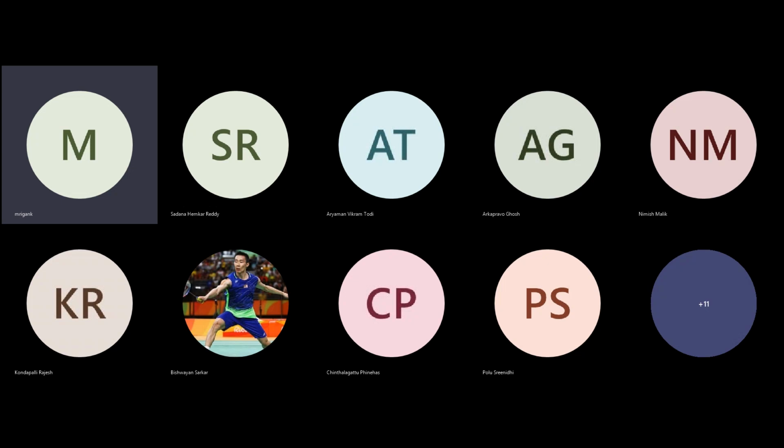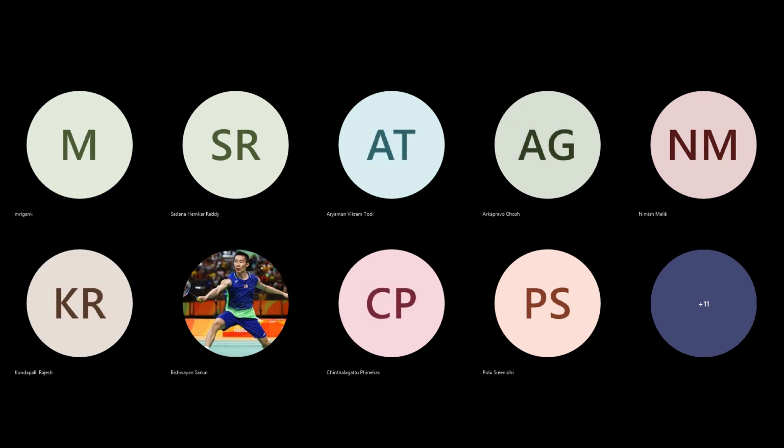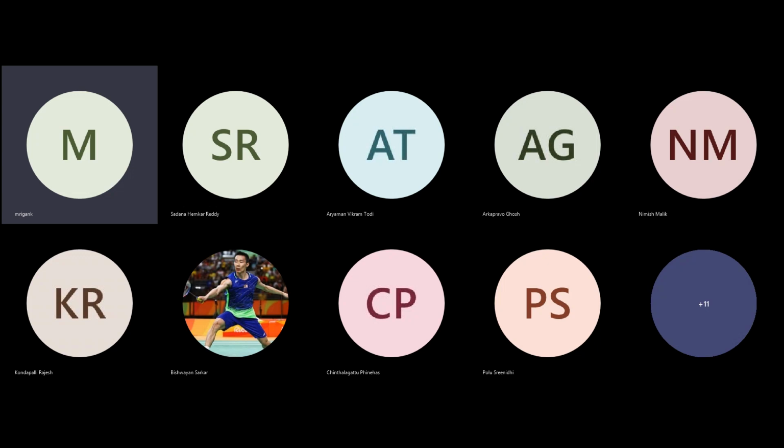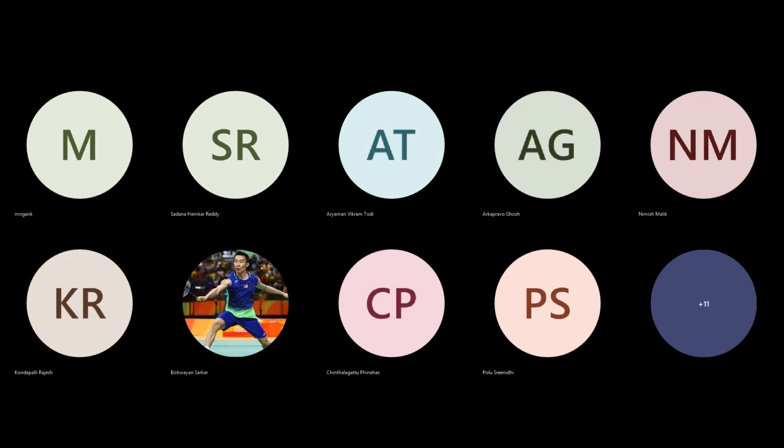So you can understand, wherever there is a requirement, we will have to keep the device size for special needs. That's why we say on the analog side, whenever you're dealing with analog signals, although the technology may be very scaled, we still have to use big devices to ensure proper operation, signal integrity, and the right kind of signal behavior, and so on. Is that clear? Any question? No, sir. Thank you.